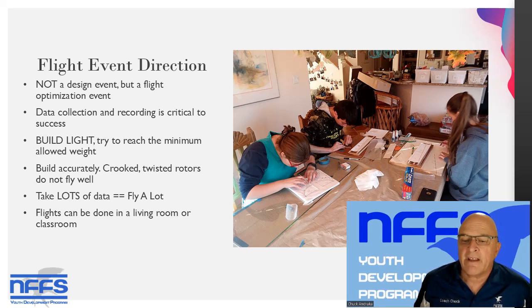It's also important to build accurately. The rotors, as they spin around, are essentially wings, and if they are built crooked and don't match each other, then your helicopter is going to wobble all over the place and waste a lot of energy just trying to beat up the air rather than flying. So accurate building using the fixtures in the kits is important. I already mentioned the importance of taking data. You want to take lots of data, and that means you need to fly a lot. This year with the helicopters, you don't necessarily need a gymnasium to fly in, so there's no excuse for not flying a lot.